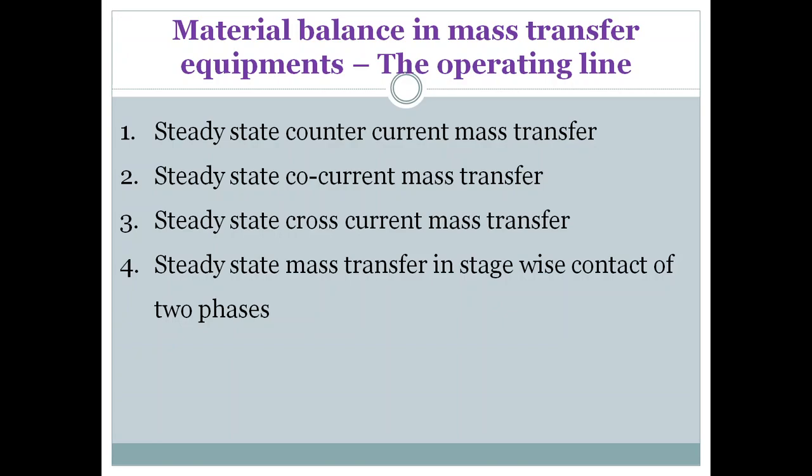In the mole ratio concept, Ls and Gs are on a solute free basis, and therefore constructing the operating line is easy because the slope is constant.